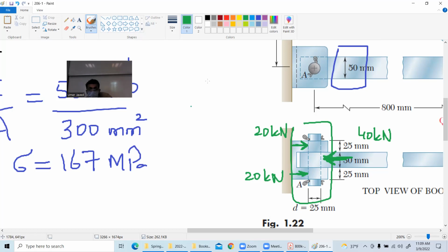Now you tell me, if this pin has to fail, how would it fail? Think about it. Yeah, who said that? Excellent answer. Shearing, knife, slicing the button. That's how. If it breaks, we will be showing everyone, you see, there are 2 or 3 pieces to this pin. So I will have a shear stress, not the sigma, tau, is equal to V over A.